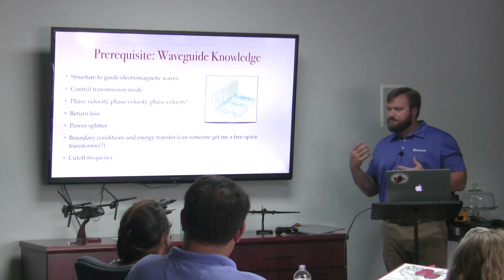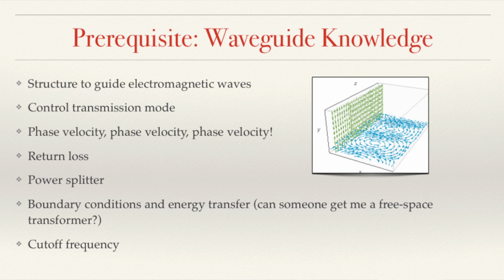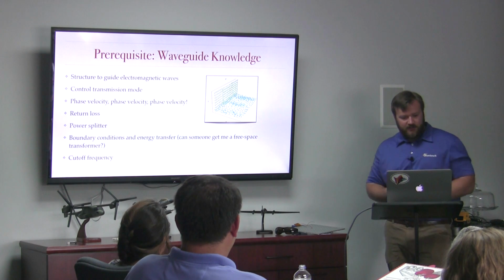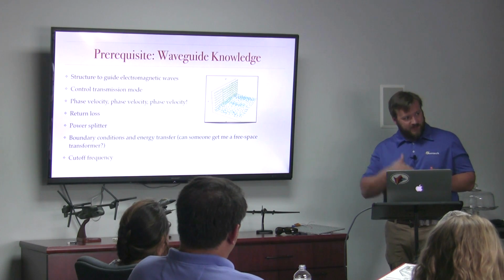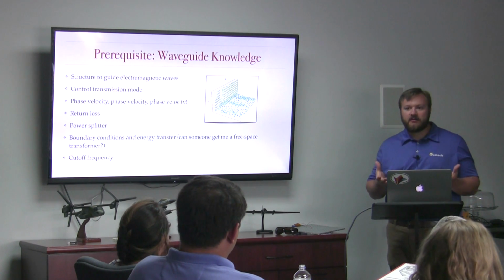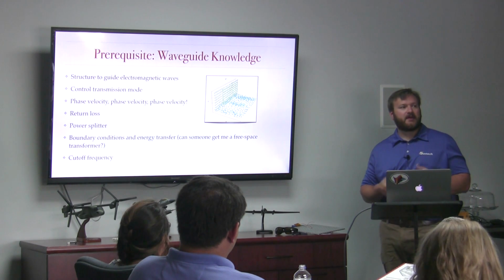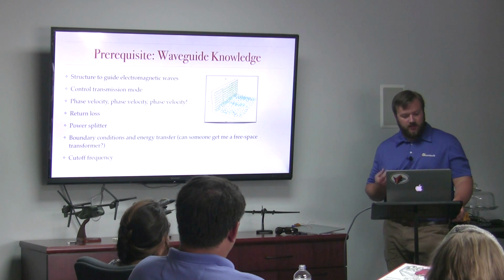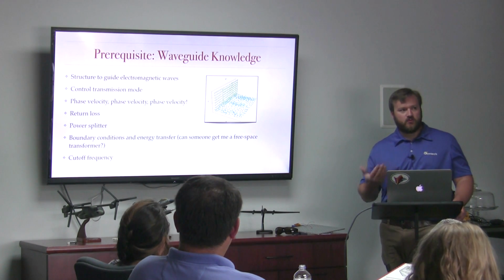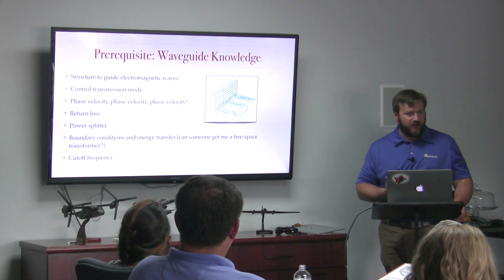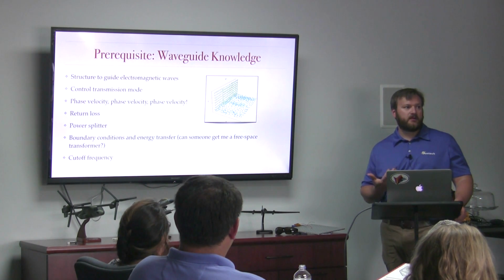So, like I mentioned, it's really just a rat race of waveguides that we're dealing with in this antenna. The purpose of the waveguide is you're bringing radiation structured down a pipe, really. And once you deal with the insertion loss of getting into the waveguide, you're really not losing power once you get into it. And we're talking about kilowatts, tens of kilowatts of RF energy with this project. So we see different cross-section waveguides. What is the difference? Well, larger cross-section means lower cutoff frequency.